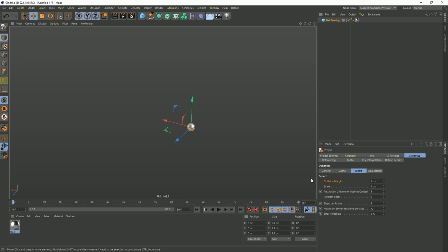I've talked about it before. But the collision margin tends to be sort of like this invisible force field around your dynamic objects that makes things calculate more accurately. But in this case, we're so small that the collision margin, the force field you can imagine around your dynamic object, would be almost as big as the object itself because it's set all the way up to 1. So that also needs to be divided by 100, which is 0.01 to be the scale.